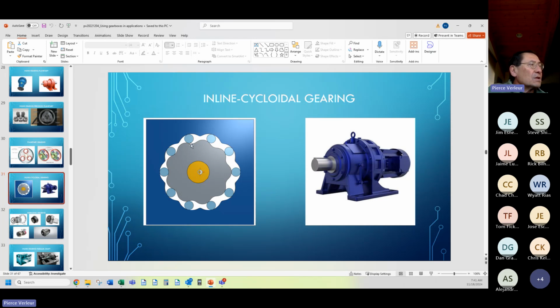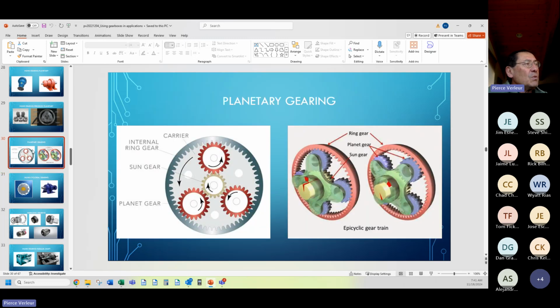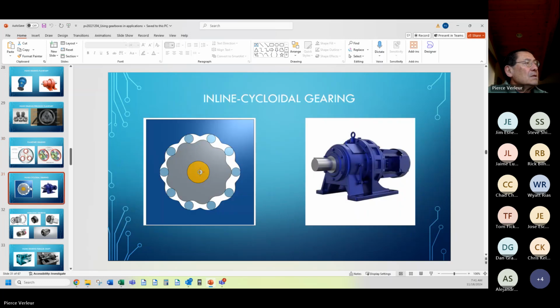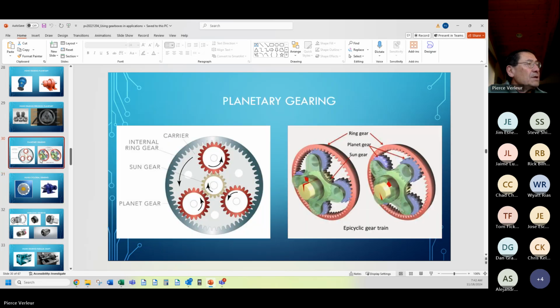When you put a lot of torque, you're basically squeezing these balls in between, these can also be cylinders, in between two surfaces with a greater degree of surface area than the point contact of teeth. So more torque, less torque. In addition, there's always contact here. Thus the zero backlash. Here, these teeth have gaps in them.